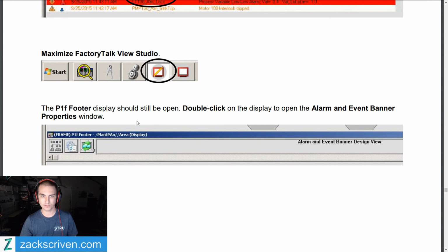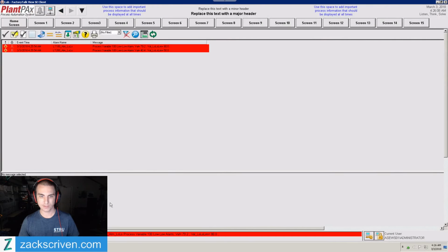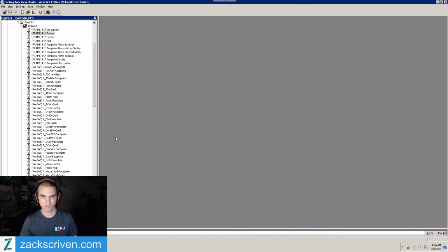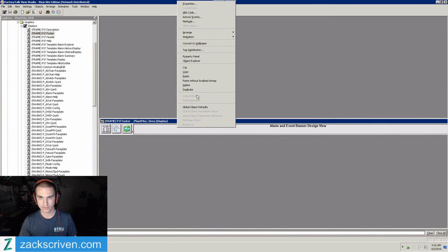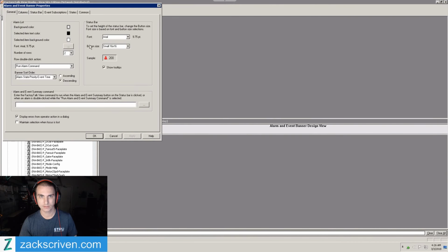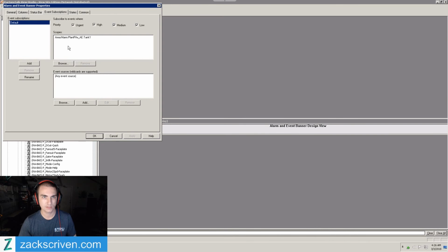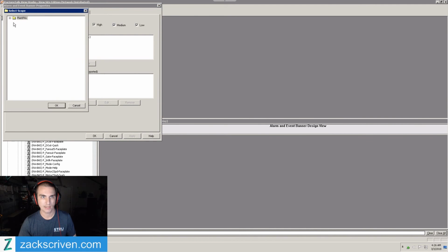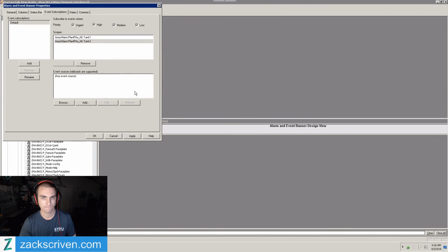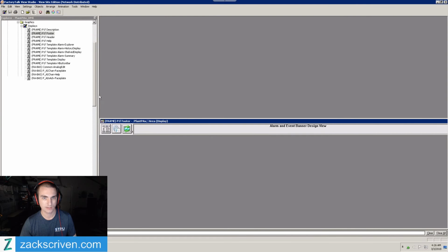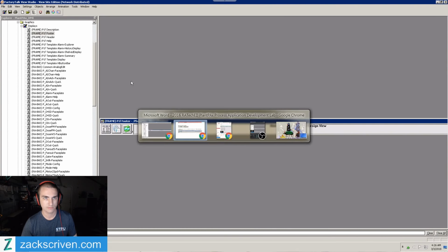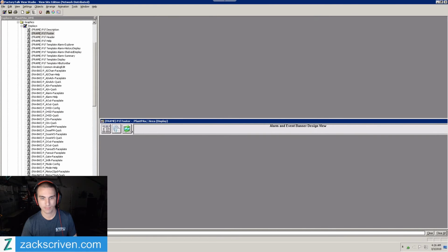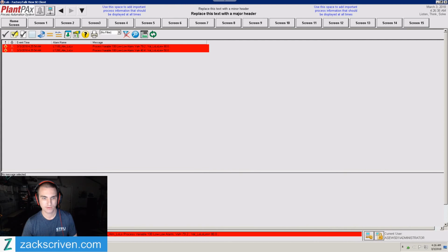Maximize the FactoryTalk View Studio. Open the alarm event banner. Go back to the P1 footer. Right click, properties, go to event subscriptions, browse. We're going to add tank 2. Okay. Oops. Apply. Okay. Save. Go back to our app. Hit refresh.